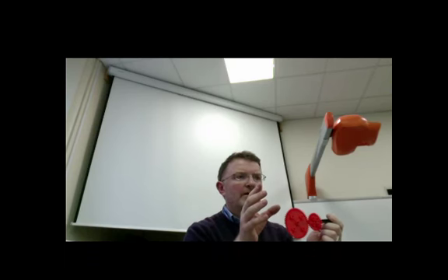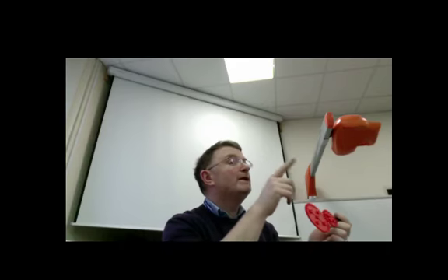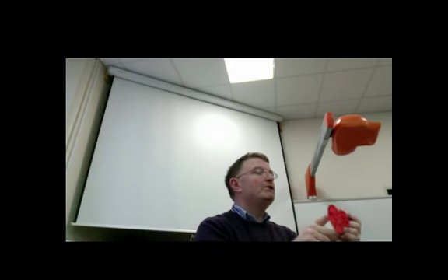It's 50 and 30. Yeah. So 50 moves 1. The ratio between 50 and 30. So it's a ratio of 50 to 30. So 50 over 30. Yeah. 5 to 3. What's 5 over 3? 1 and 2/3. So this wheel should turn 1 and 2/3.